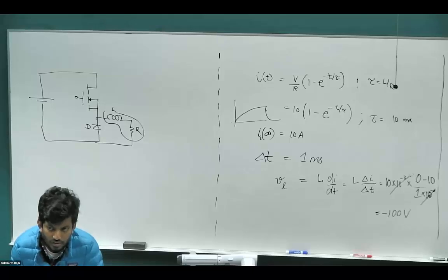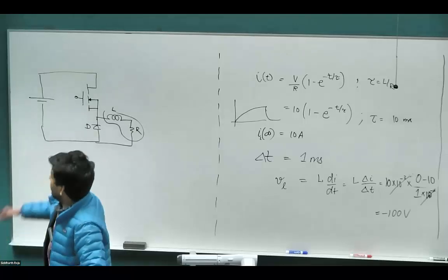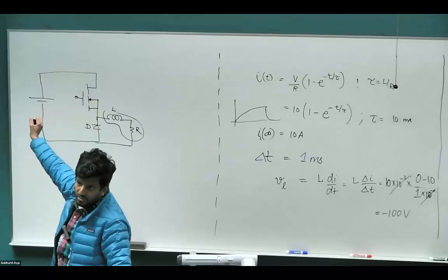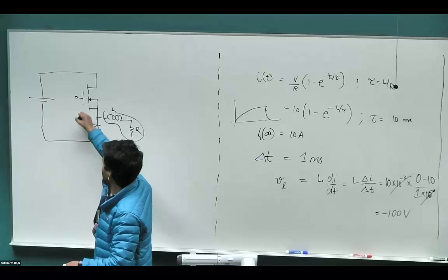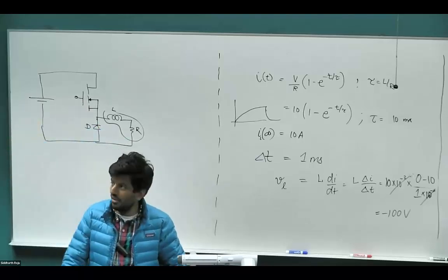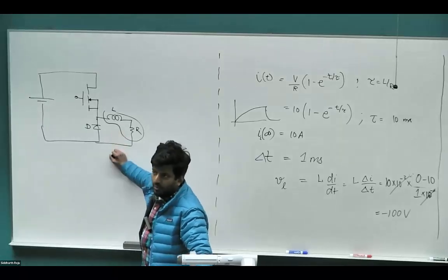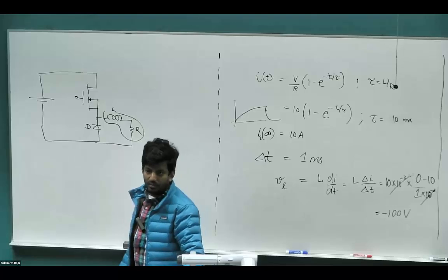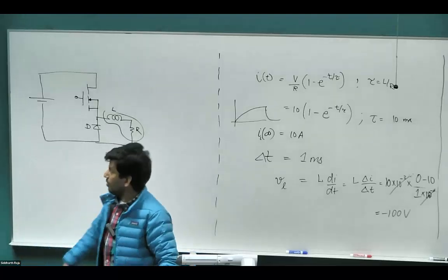A lot of FETs have diodes already in them. A lot of what? A lot of MOSFETs, like power FETs, already have. Yeah, all MOSFETs have a body diode integrated. Yeah, that's the missing portion. Oh, okay. Sorry. So you can either use a MOSFET or an IGBT for power applications. IGBTs you can get without a body diode. MOSFETs you cannot go without the body diode, it is intrinsic. I was just curious why you also have an external diode. We'll get to it. Okay.